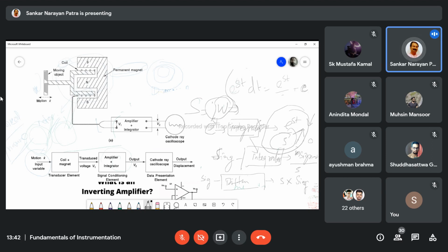If the signal is a lower frequency signal, S is smaller, so the output of the differentiator will be smaller. Suppose S is a fraction, 0.1, then the output of the differentiator will be multiplied with 0.1, so it will be 1/10 of this. So the lower frequency signal will die out in a differentiator, but in case of an integrator, the higher frequency signal will die out. Now tell me, what is the behavior then?